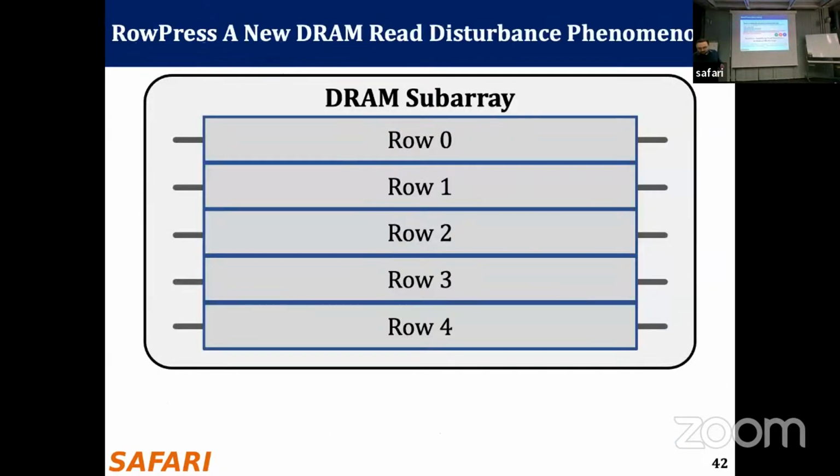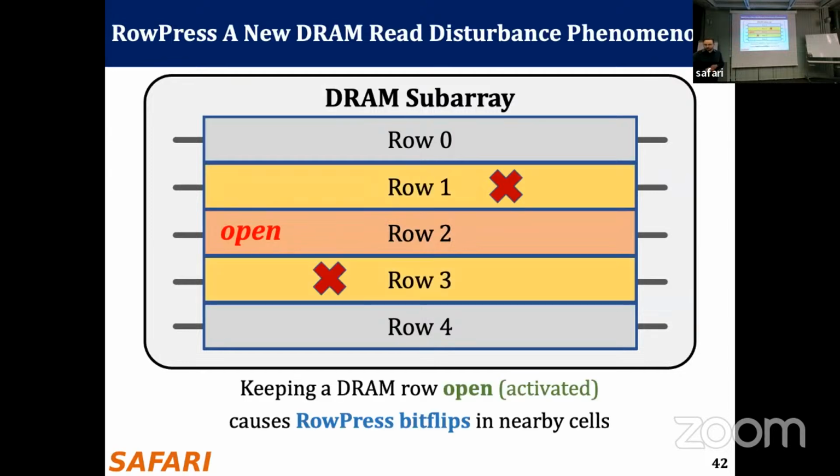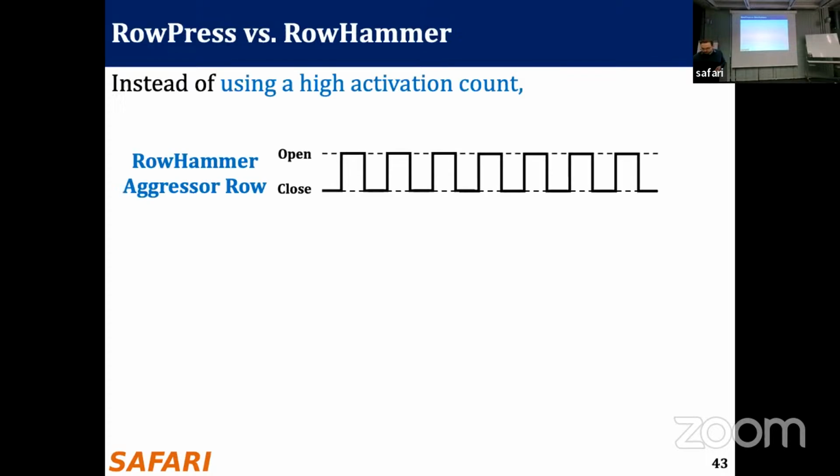Okay, yeah, this is that RowPress paper. And in the RowPress paper, it's shown that you activate this row, and then you don't close it. You wait a very long time, around 30 milliseconds, and then you can reach bit flips with one activation count. So it's quite impressive.